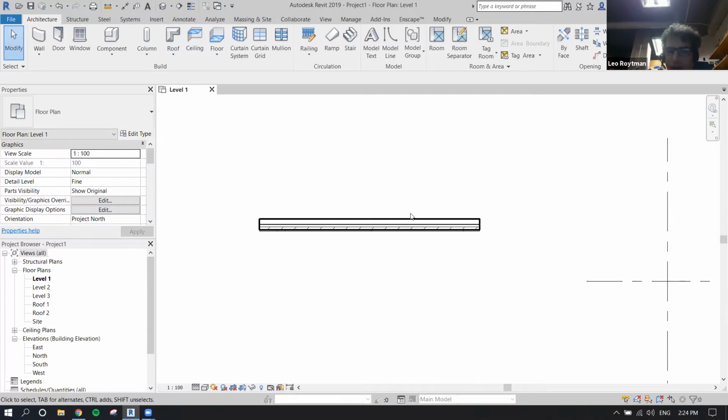So for now, until you really understand what this level of details and all this information about structure means, and unless you really want to show this information, use basic walls without this filling information, because otherwise it will be destructive and won't help you in communications with your professors.